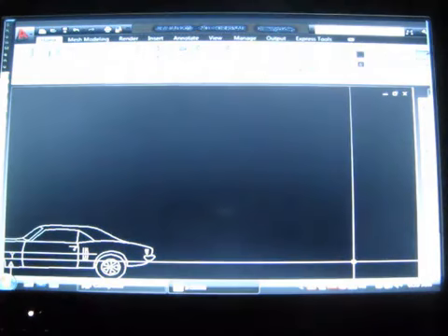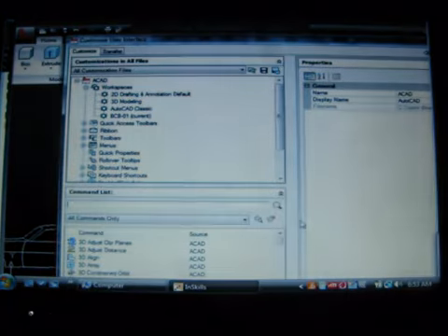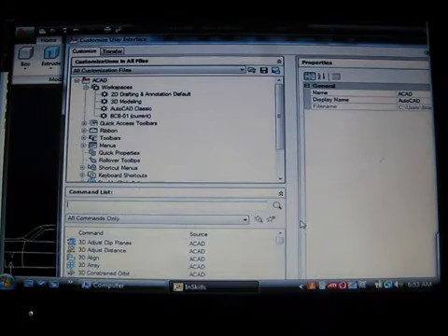To further customize your new workspace, you'll need to click the Customization button. This will bring up the CUI, or the Custom User Interface Manager. In here, you can change the characteristics of your workspace. I won't go too deep into this because of the scope of it, and it's extremely difficult, but for a few things, it is very easy to do.